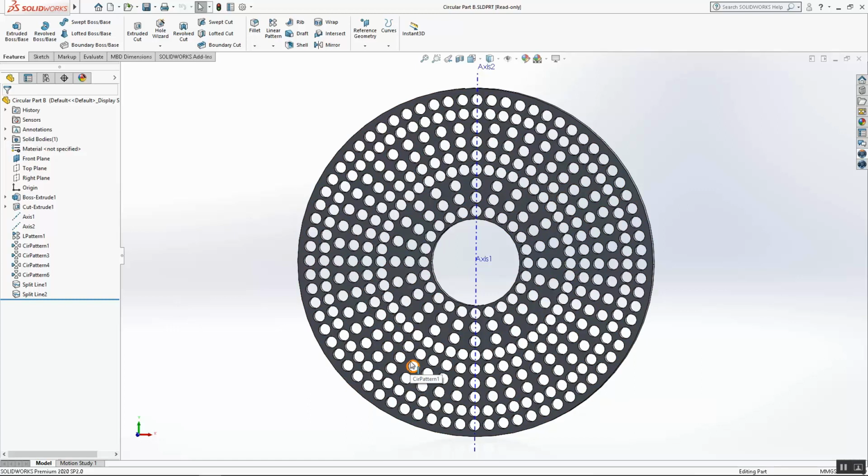So when that displacement is applied, these circular cutouts throughout our structure are going to potentially collapse on one another. If we were going to set this up inside of SolidWorks simulation, we would need to specify contact pairs. So you'd have to use a little bit of insight into figuring out which faces could potentially be collapsing on themselves, or which faces could be coming into contact with another face in another circle.